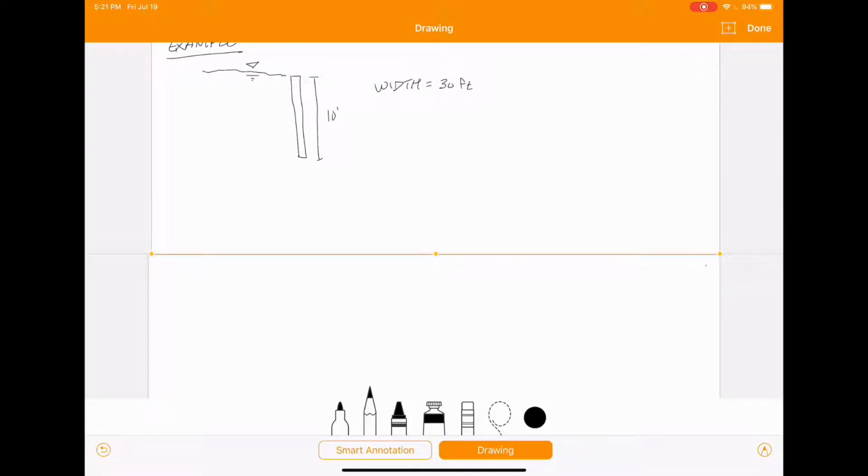All right, so the first thing we need to do is find the pressure at the critical points. So in this case, we're going to want to look at the top of the gate and the bottom of the gate. But we know at the top that the pressure is going to equal 0 because your depth is 0 at that point. So we automatically know that all the other equations there are going to be 0.